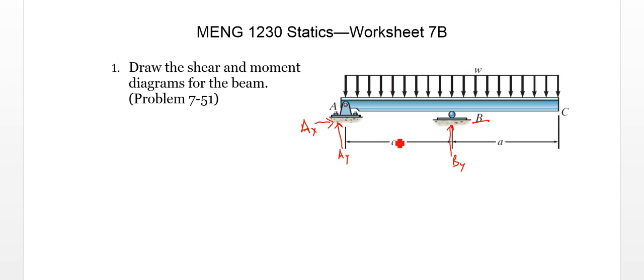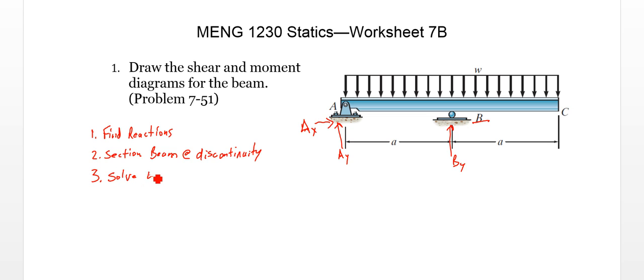So if you recall, our approach here: 1. Find the reactions. 2. We'll section the beam at each discontinuity. 3. We'll solve the equations of equilibrium.